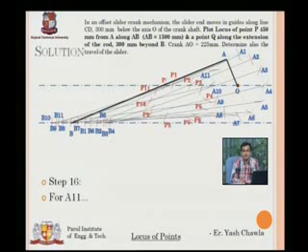So again we can see that we have all the points in association with the position of the slider, the position of the connecting rod, the position of the crank. For crank positions A to A11 we have different positions of the slider from B to B11, and at the same time the position of P is determined by the red markings or the arcs which are cut on the connecting rod, from P to P11.